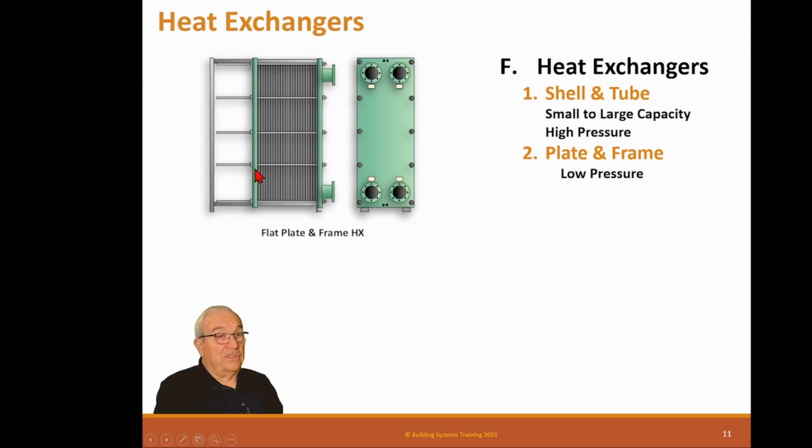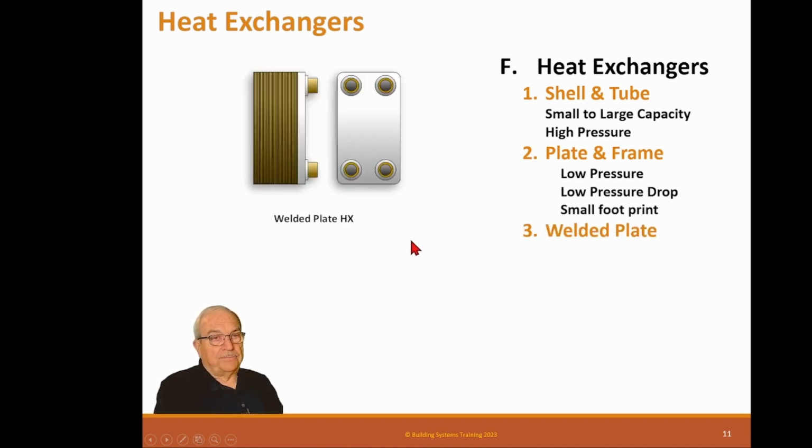And the reason is you may have to compress this thing from being 4 foot when you put all the plates in, and you really need to be at 2 foot so it doesn't leak. So you have to bolt this down and compress this plate, and it takes a lot of time. You wear out a couple of guys doing it also. But these also have low pressure drop. They can be in the means of 5 to 6, 7 psi drop, which is small for a heat exchanger, and have a very small footprint.